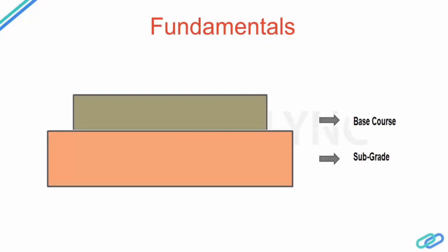When we compare flexible pavements to rigid pavements, in rigid pavements we may have only one layer, that could be a granular layer or a cemented layer itself. But a flexible pavement, that's a bituminous or asphaltic pavement, has a base course consisting of multiple layers. We can have a sub base course, then a base course. That base course can also be divided into a granular course and an asphaltic or bituminous course. And finally, on the top, we have the wearing course.